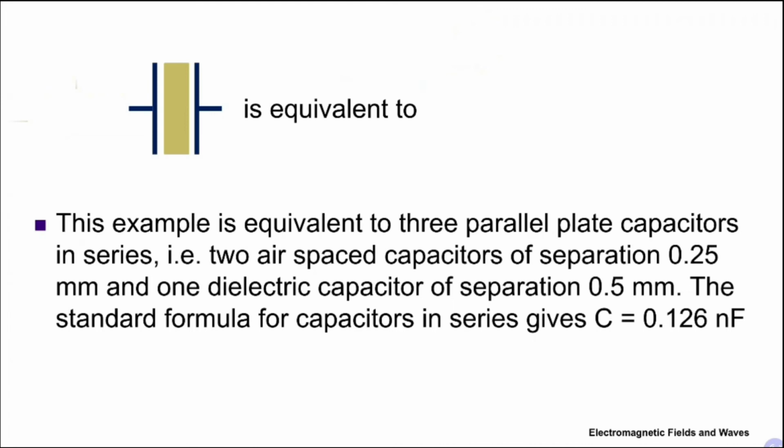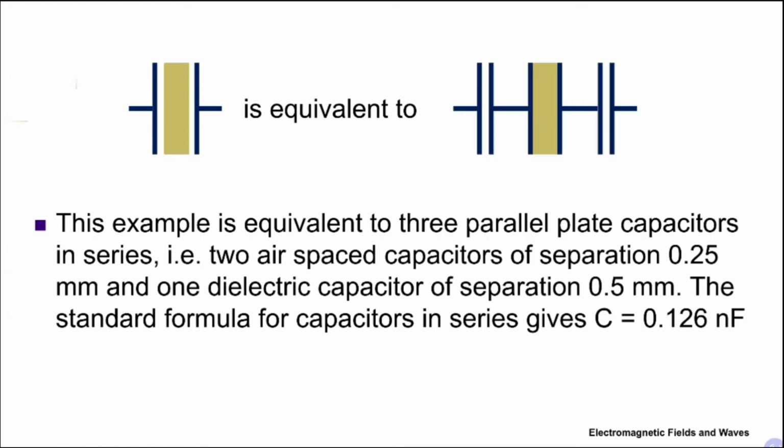Okay, the plate that we have just now, we have one dielectric in the middle and both sides with air gaps. So this is equivalent to series capacitors. So we have epsilon 1 here, 0.5 millimeters, and then this is 0.25, 0.25.